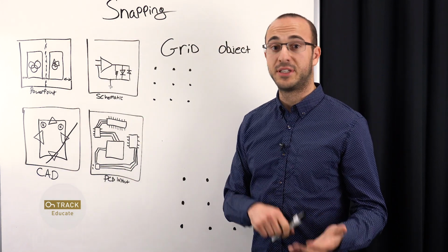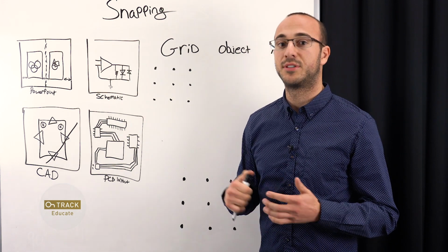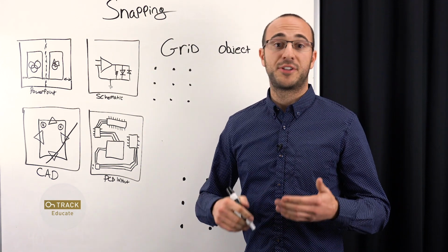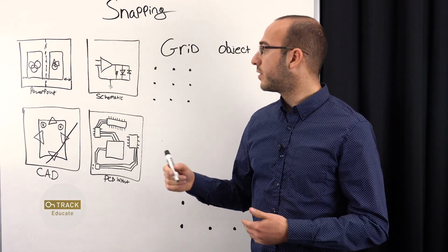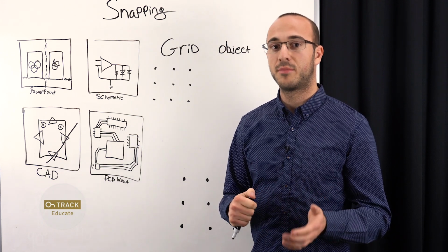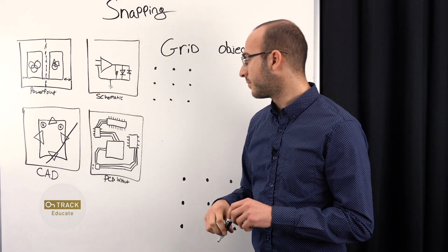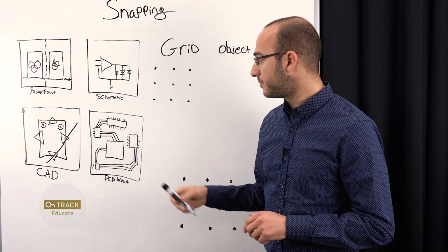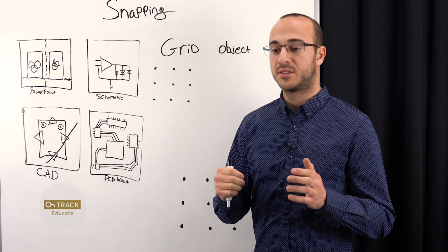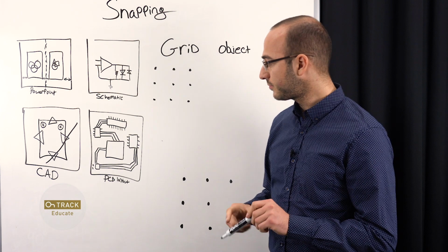In terms of PCB design, snapping is really essential when it comes to the schematic. If you want to give your schematic to your manufacturer for debugging, you want them to easily follow along. So if they encounter any problems, they can quickly find a solution or find the problem. In terms of layout, snapping can really maximize your routing channels and minimize the board space.